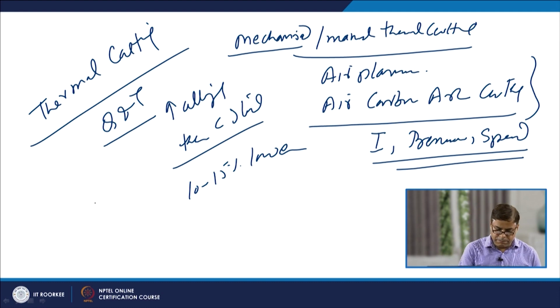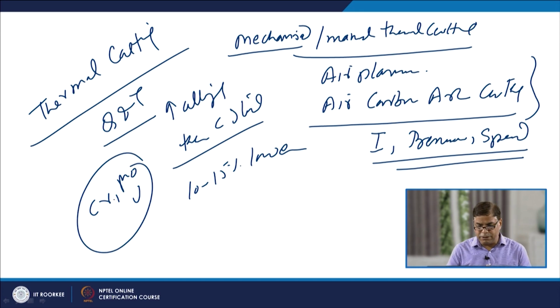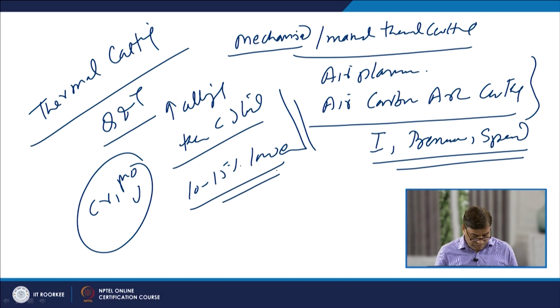And sometimes the presence of chromium, molybdenum, vanadium in these steels interferes with the cutting. So, that must be cleared, or to facilitate the cutting in the presence of these elements, we need to cut down or reduce the speed, especially if the cutting is erratic.